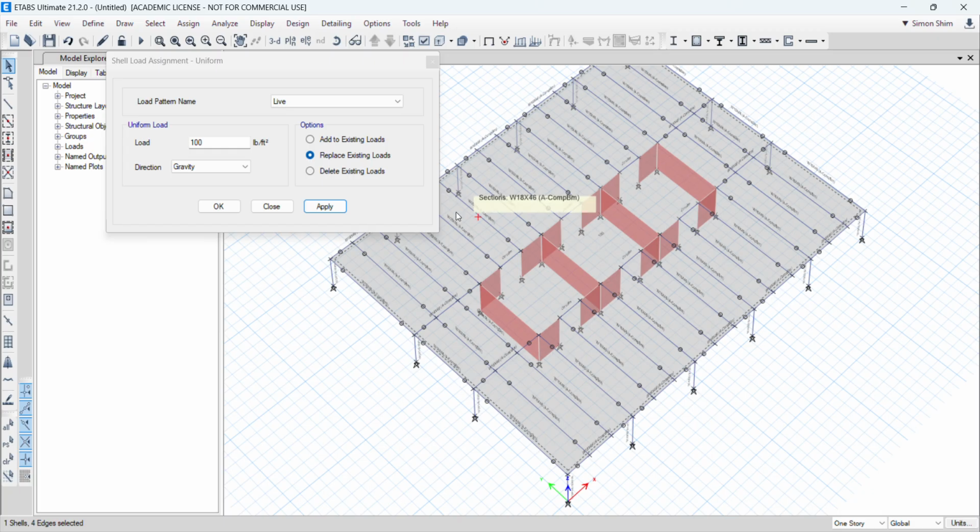Repeat. Select this. Now construction live load. During the construction phase, I assume something like 20 psf live load. People walk around. They carry the material. So the steel members, when the concrete is poured, people still work along on the metal deck. Concrete is wet. The people move the equipment around here, there, right? We need to address those. At that moment, the steel alone, the steel beams have to be strong enough and stiff enough.